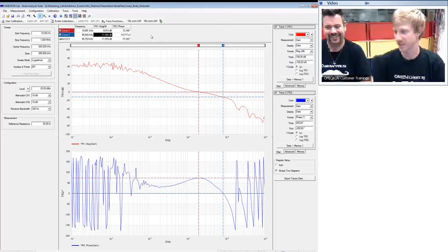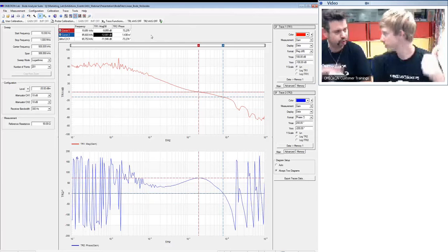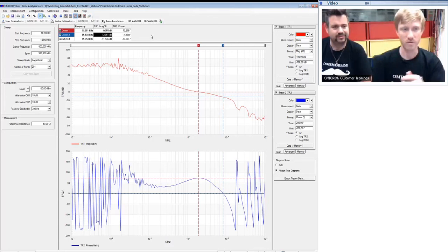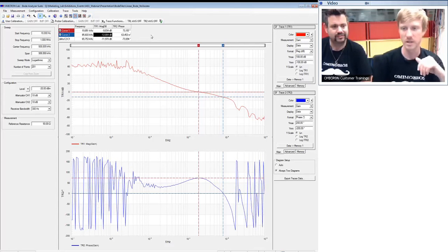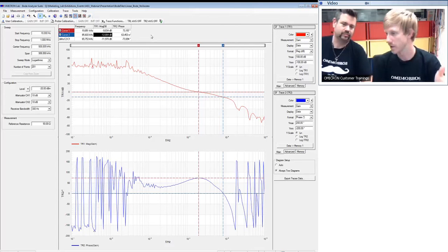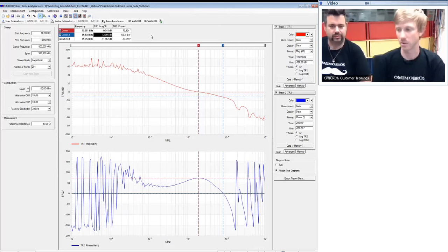But in general, you can say with 45 degrees, you have only one period, one overshoot. So you don't have multiple periods of ringing. If you have less than 45, you will get more and more overshoot. And if you have more than 45, you will get even less overshoot. With more than 70, you generally don't have overshoot anymore. Then you're getting a very damped system and a very good response. So if you prefer to have no overshoot, then you should have more than 70 degrees of phase margin.